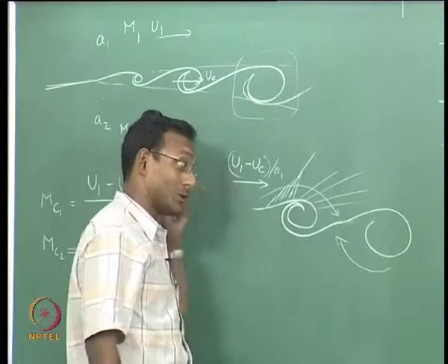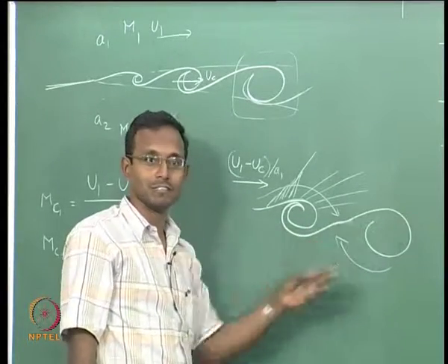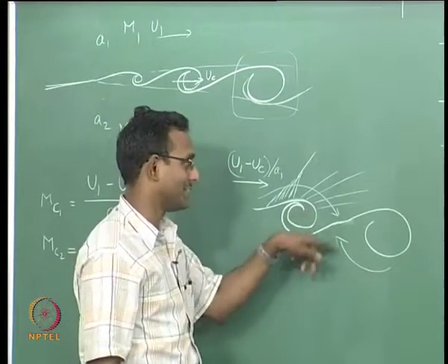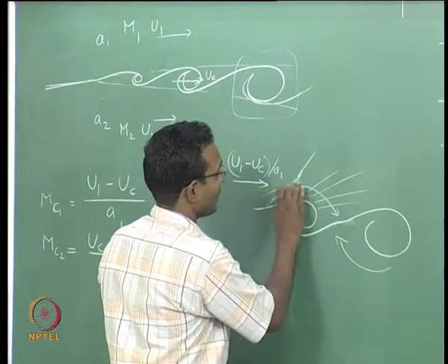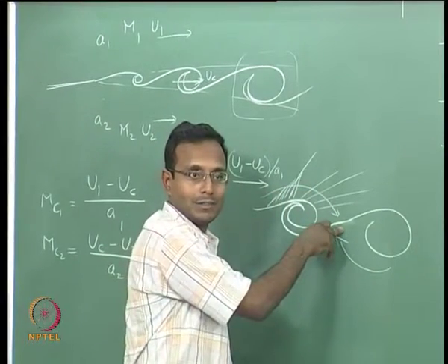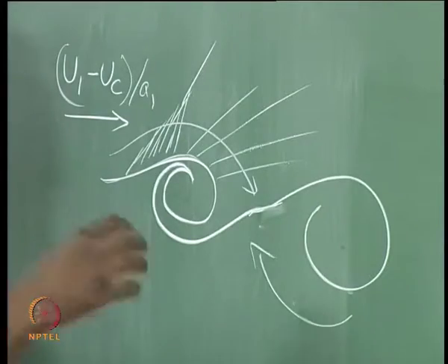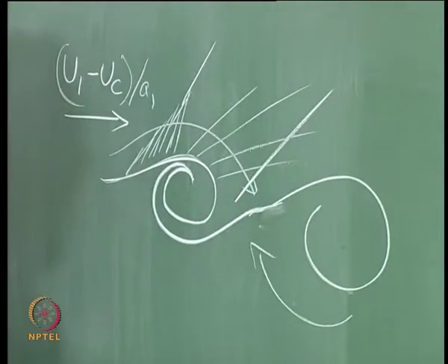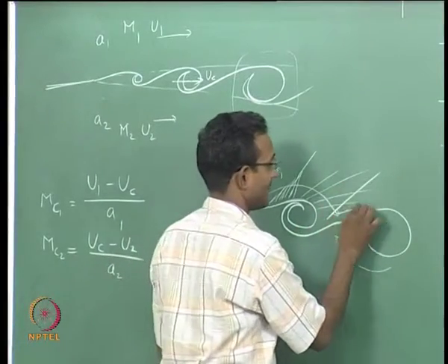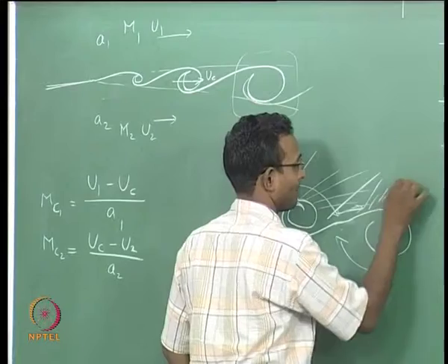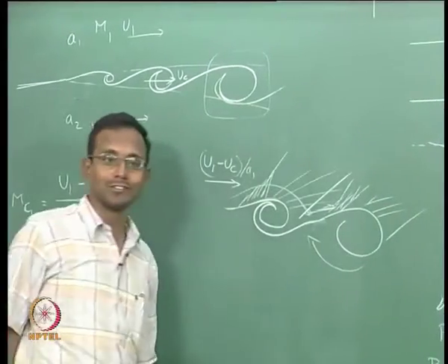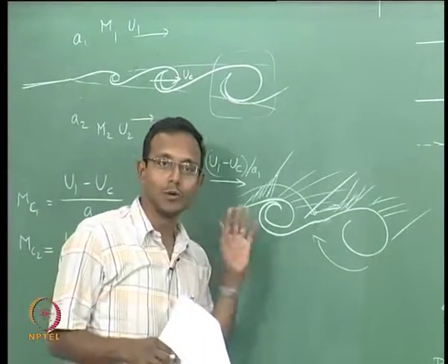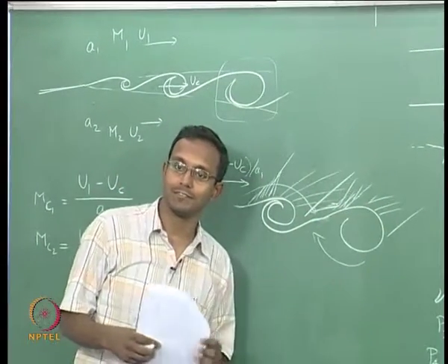Overall it is also having a convective velocity UC, which we have neglected, we have removed, so we can see this particular thing happening here. So what will happen, it is expanding, becoming higher velocity, and suddenly it has to stop. If it has to stop, there has to be a shock again sitting there, so that it will immediately turn out and go out that way, and then the whole procedure starts again. It is again seeing things, there will be initially compression and then expansion, and then another shock, all that kind of stuff will start happening there. This whole structure keeps repeating like this.